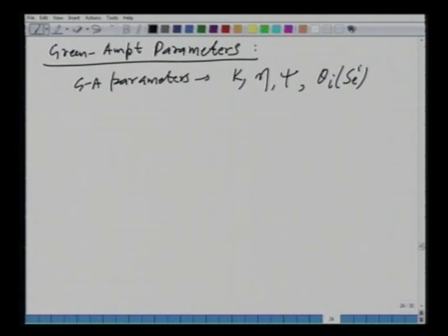Normally this psi is a function of the moisture content. Most of these parameters, we consider them as constants. Let me write that first. That is to say, their values are not changing as a function of time during a rainfall event. What is a constant? Which does not change with time as far as these parameters are concerned. However, we know that the suction head and the hydraulic conductivity can change as a function of time.